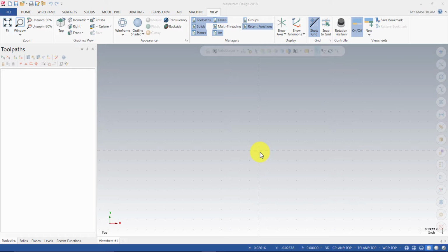We will only create the upper profile of the part. Only half of the geometry is needed to create the necessary toolpaths to machine the part. Geometry creation commands such as line endpoints, line parallel, rectangle, fillet entities, and trim will be used.